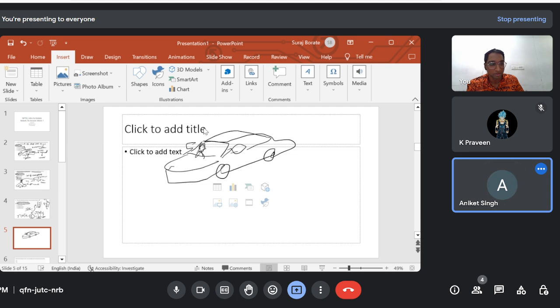Yes, sir. So you won't reach the destination, right? You will go and hit somewhere because your eyes are closed. Why is that happening? That is happening because there are some disturbances. Even if you remember all the commands, when to turn the steering and all, if you close your eyes, you will hit something. Why? Because there are disturbances. There will be some small pothole, or the car will not behave exactly every time the way it is supposed to behave. So why that is happening is because there is no feedback.